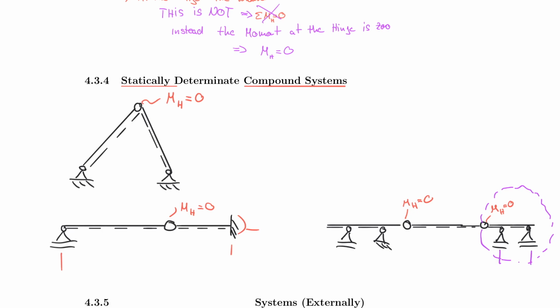That would give you one equation with two unknowns, and let's call that equation 1. But you can also have your equation 2, because you know that your moment there is equal to 0. And in this equation, you have the very same two unknowns. And so you have two equations with two unknowns, which you then can solve. And you can find the answer.